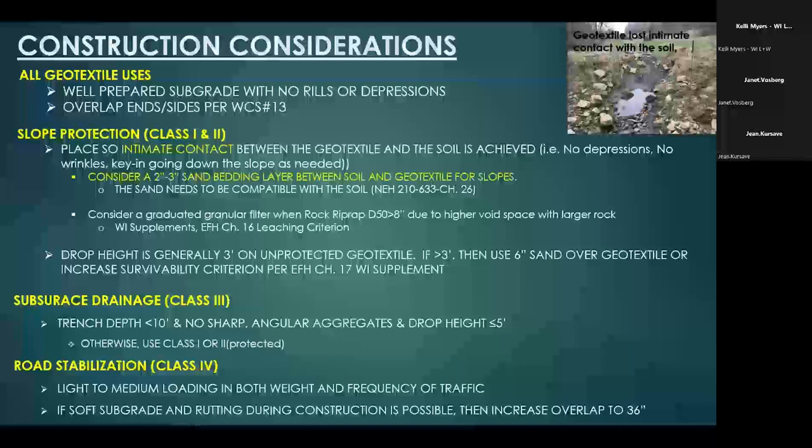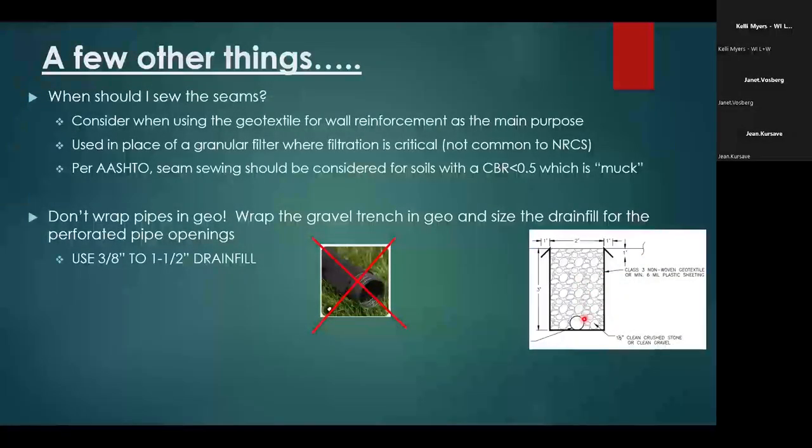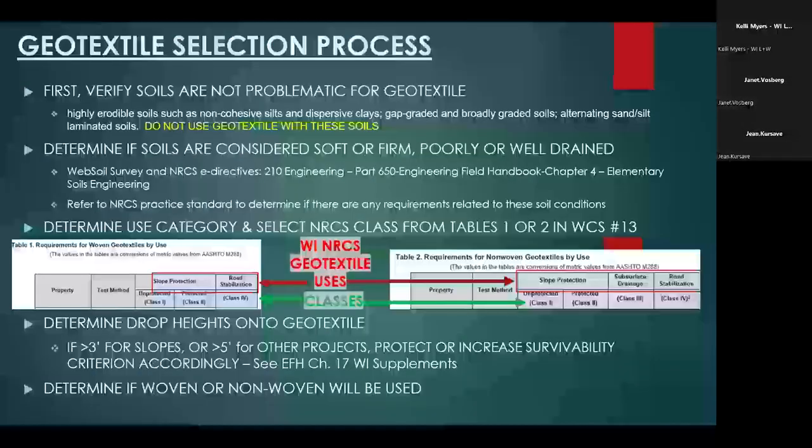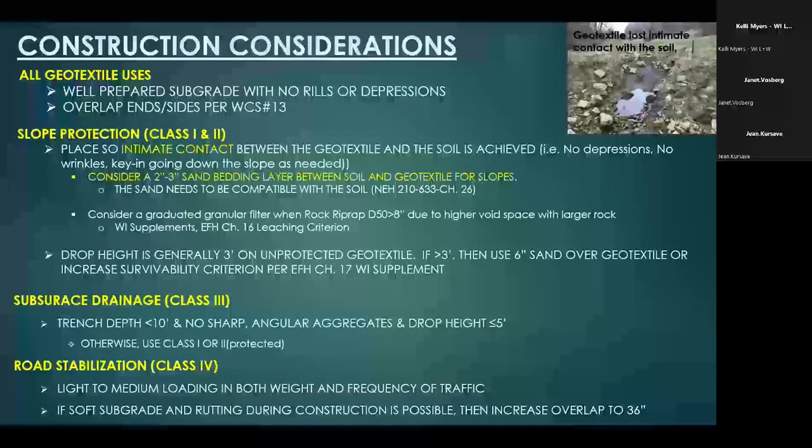I would use, let me just back up a couple slides right here. If you're going to use geotextile, put that around the trench, make a trench and fill it with stone and put the tile in there. You'll have much less problems with clogging. Does that answer the question? I think so. Okay, great.